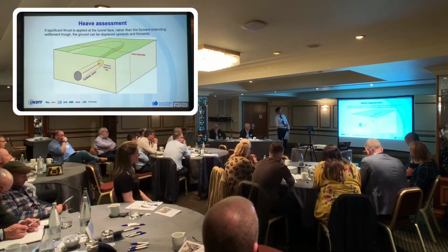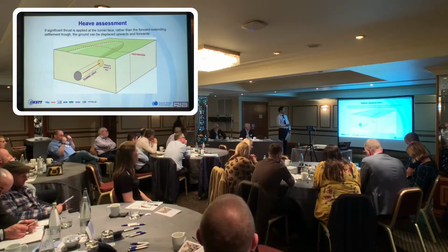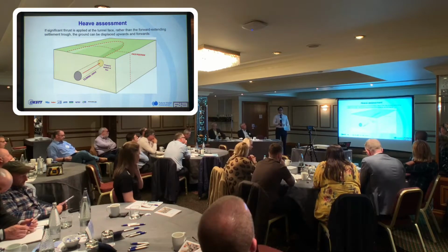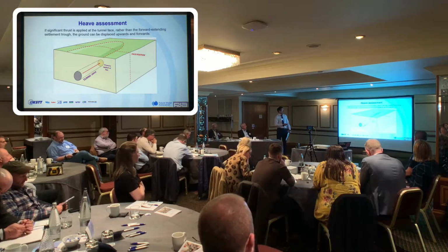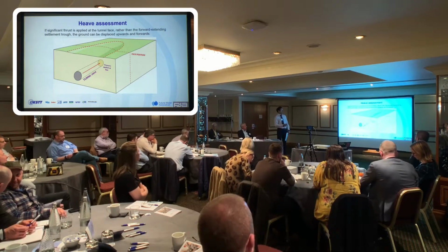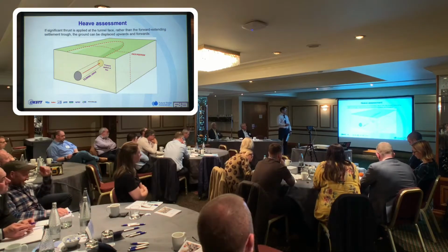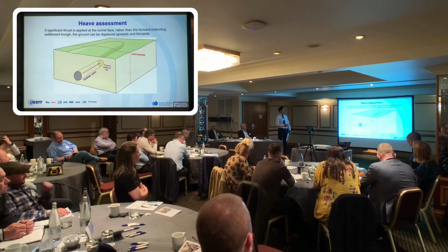Again, with settlements, there's the possibility of heave. If you're applying thrust at the tunnel face for the forward motion, and your forward progress is limited to the force induced, the ground's got to go somewhere. If it's not coming out the back of the machine, it's got to move. You can have situations where heave can occur, again, with various considerations based on ground conditions and the stiffness of the material you're driving through.